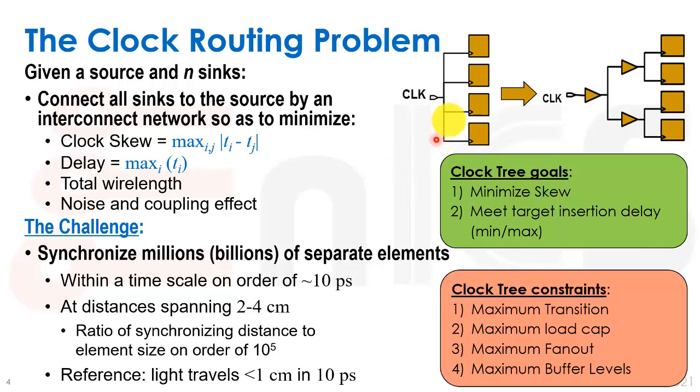Now we come and we build this clock tree, and it changes everything because it introduces skew. Not only that, it can also cause hold violations. We didn't have any hold violations basically before. We didn't even check hold usually during the first stage of the design because it was irrelevant without having a clock. But once we introduce skew, then we have those deltas in our setup max and minimum delay equations, and they're going to cause us setup and hold violations.